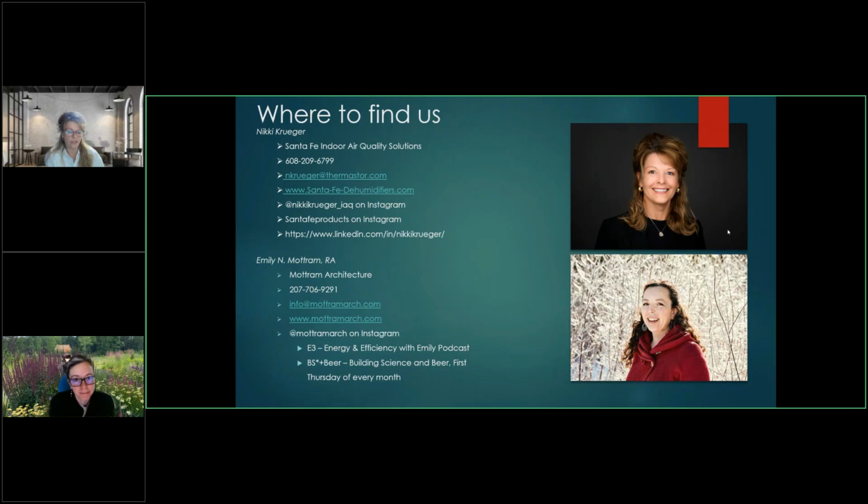Yeah, I would use an ERV for the ventilation, and then, depending on the climate zone, I would use a dehumidifier to dehumidify the house separately. That's pretty tight, but again, depending on where you're at, you might still want to do a slight positive pressure if possible, because as soon as we go negative, we just start sucking everything from the outside in through our walls.